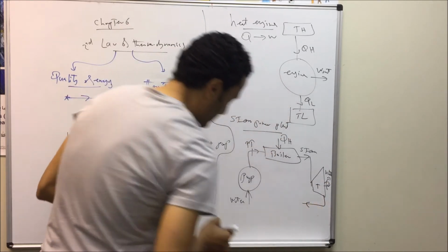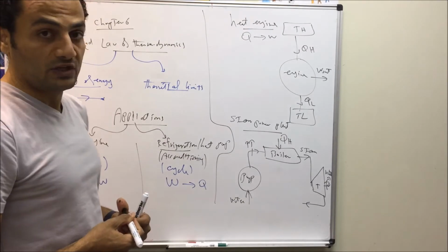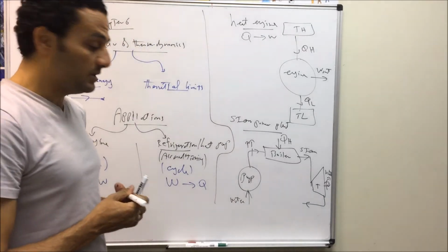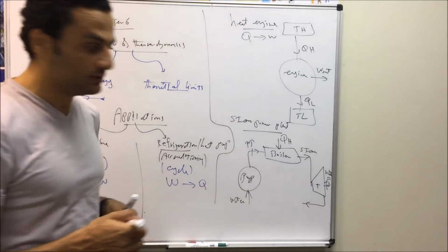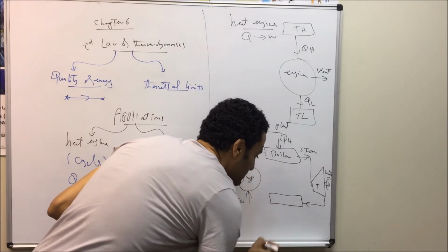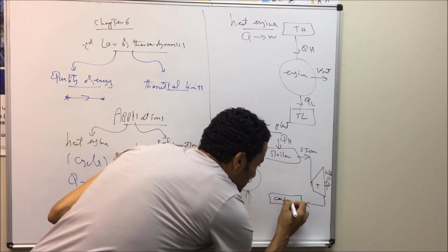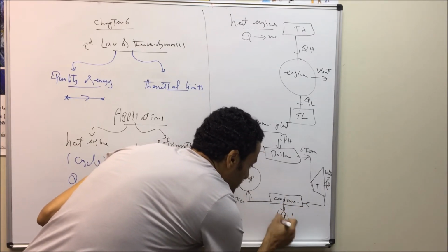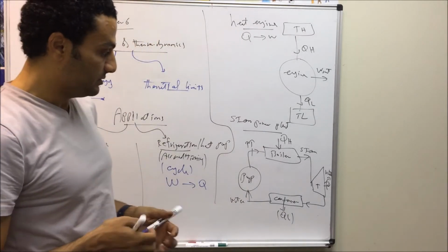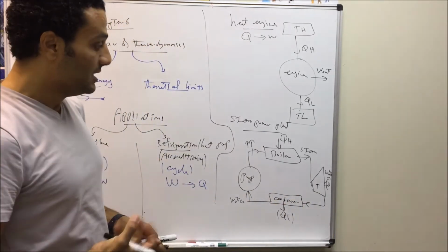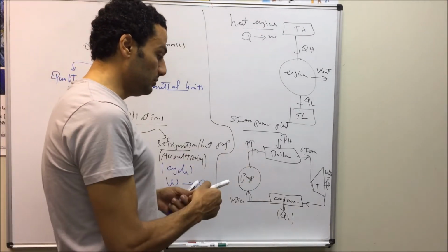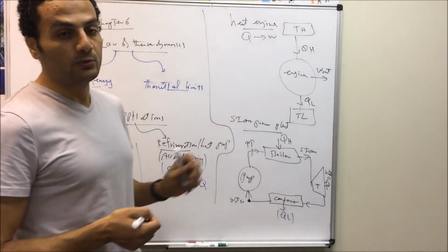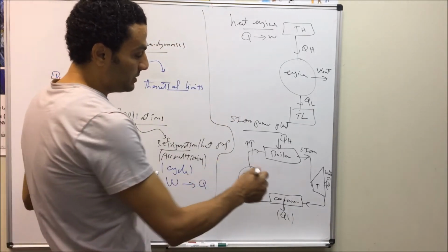The steam leaving this turbine is usually at a saturated state, so we still have a mixture of steam plus water. In order for the system to work on a cycle, we have to get back to the initial state, which is the water state. So we have to reject some heat inside the condenser from this saturated steam mixture. Part of this heat is rejected through a cooling system in a power plant. We just cool down this steam in a condenser, so all of the steam will be condensed and get back to the same initial state, which is water. So the cycle can be repeated again.